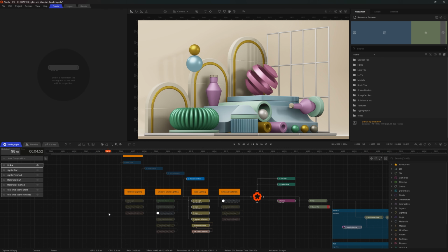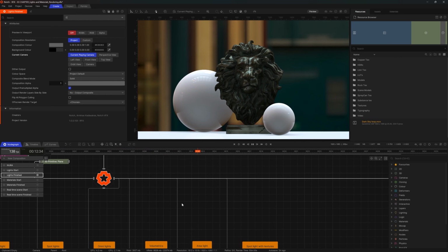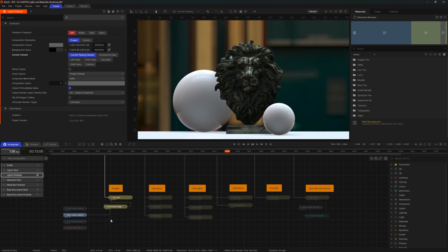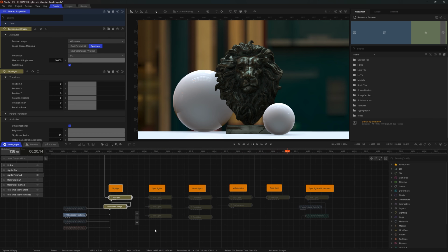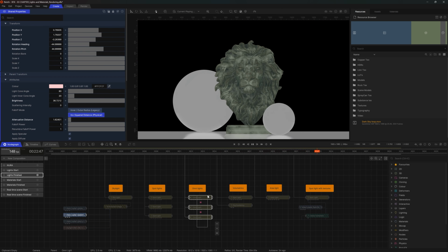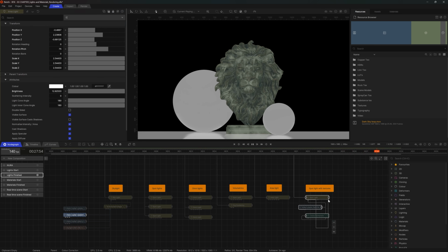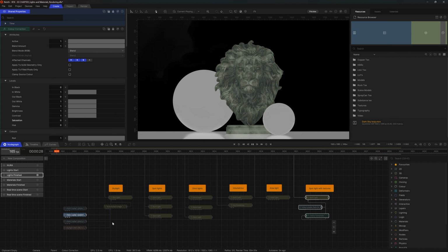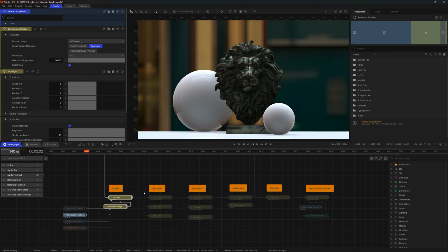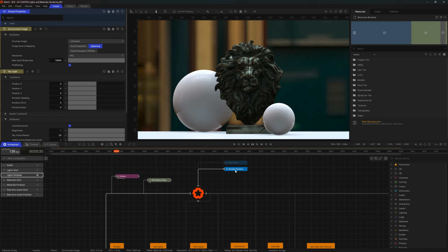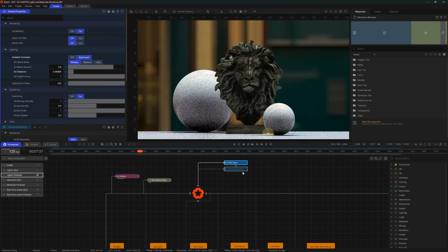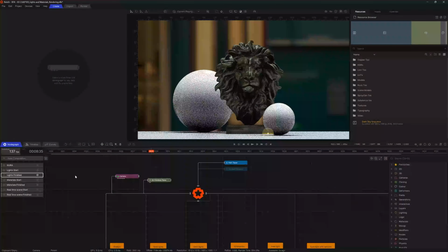So with all of that out of the way, let's get a bit more hands-on and look at the lighting in Notch. I will start by heading to Lights Finished Composition. This is our reference point for different light setups that we will be trying out. So we will be covering skylight, spotlights, Omni Lights, volumetrics, area lights, and video or texture emission from spotlights. For these workshops, we will focus mainly on standard renderer. Flick back and forward to Path Tracer for comparison and reference. So let's get started.